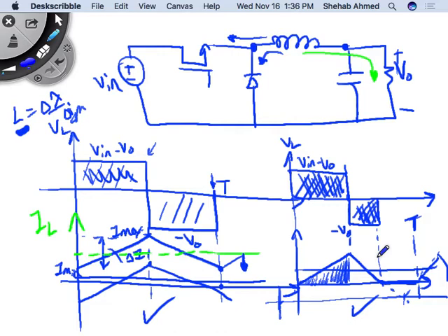In discontinuous mode, if your controller can operate in continuous and discontinuous mode, you can remove the load, and the converter will operate in discontinuous mode, bring the average current down, without a minimum limit. I don't know if I'm making sense. I'm just saying, in continuous mode, you always have to have a load connected, right? In discontinuous mode, I can remove the load.